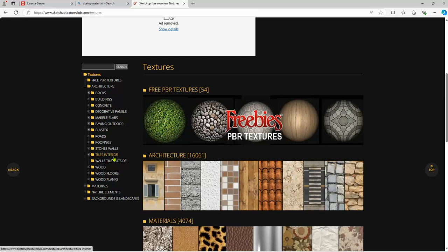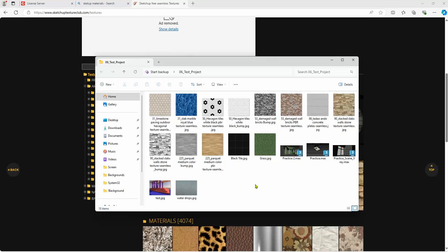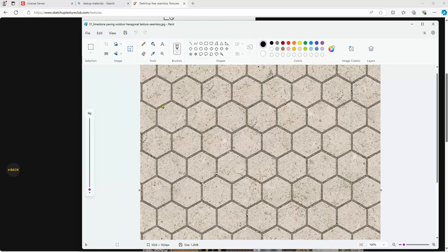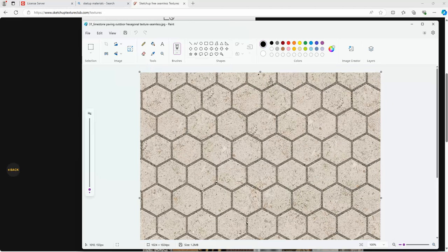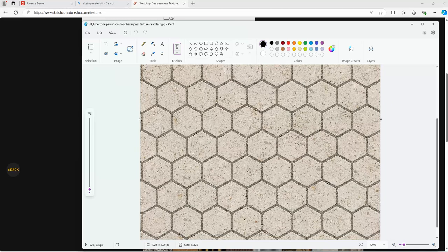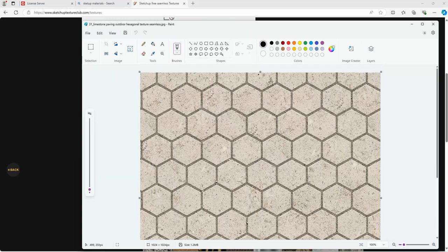So what do you typically do? How do I create the illusion of the whole wall being covered in brick? What do I have? Let's say my floor is this. What is this? Some type of paver, right, for the floor. If I'm going to pave 10,000 square feet, I can't have a map that size. So this is simply a small, squared piece of this material. What's important about this material when it maps? The scale, yes, but how does the material truly work, really? It repeats, right, the pattern.